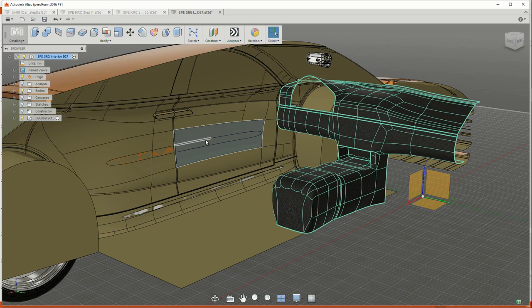Yeah. So I don't know. Does it do that? Well, it does do the conversion. So when you pull it in, I believe it's a BREP object inside of here. So it's done the conversion of that. The surface patches look about the same, and this is about a 150 megabyte Alias file, and it comes in at about 20 megabytes inside of here. So there's stuff that is going on inside of there. So in answer to your question, yeah, it does some conversion, and that's why we can actually do modification of it. You wouldn't want to round trip that back because you're probably losing something.